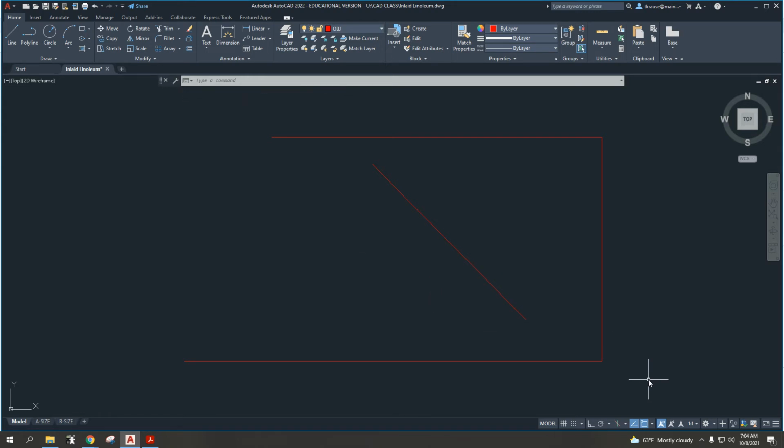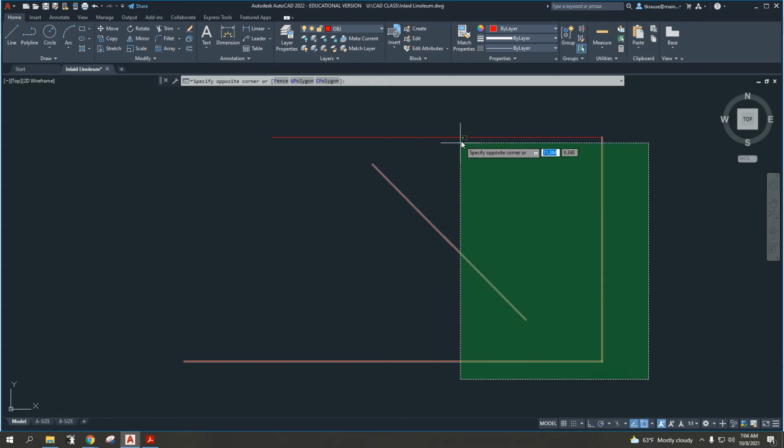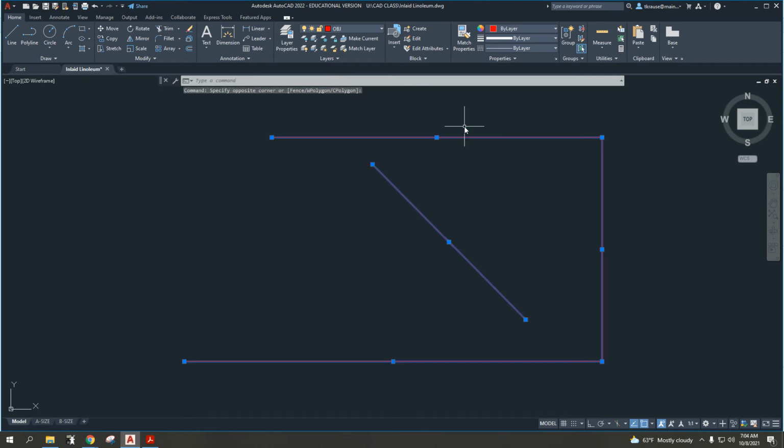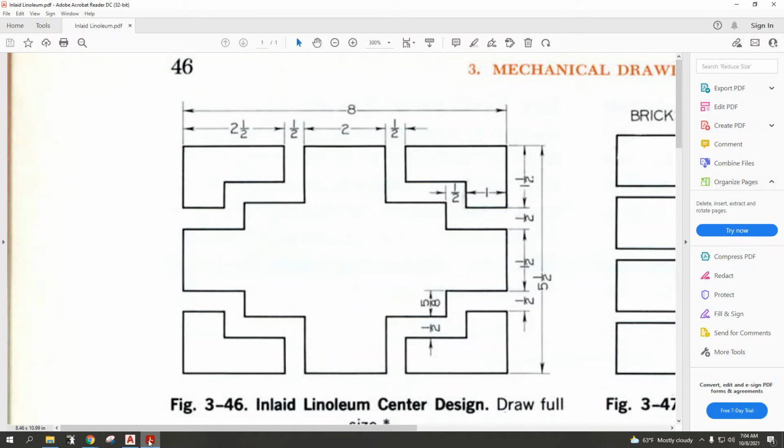If I want to left click and drag to the right, you'll see I have a green square with a dashed line or hidden line around the outside. This is another selection box, but this selection box only has to touch something and it will select it. Okay, so again, left click to finish that and delete key to delete. So some basic stuff there, but let's get drawing.